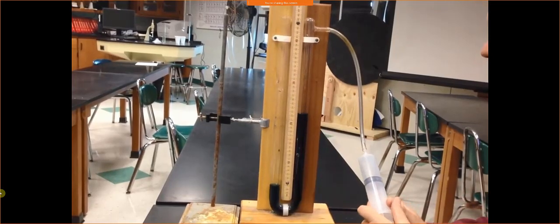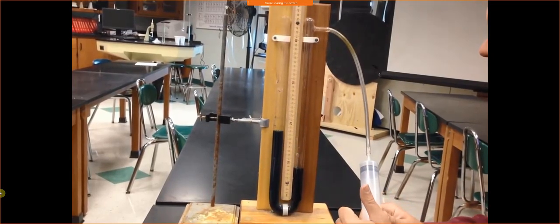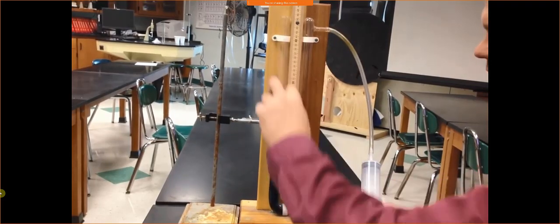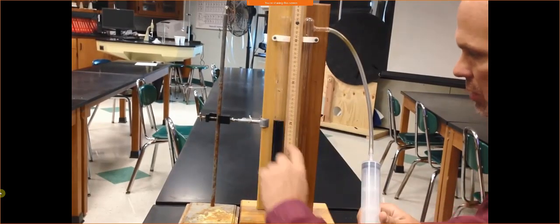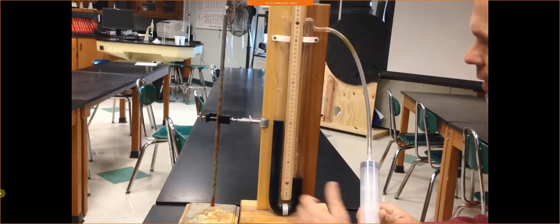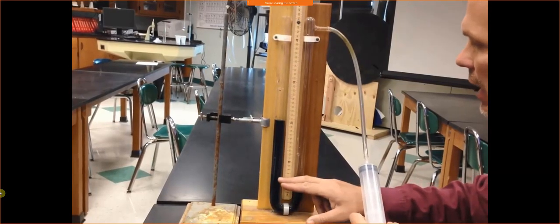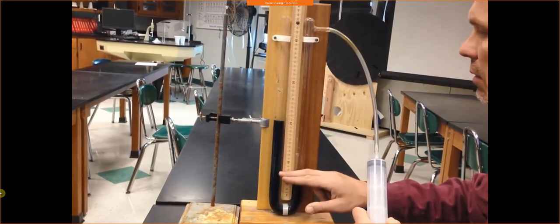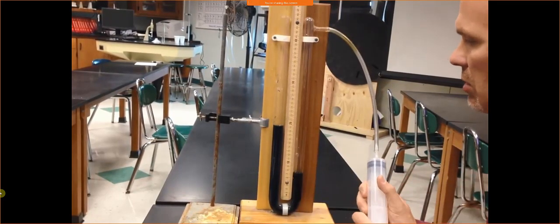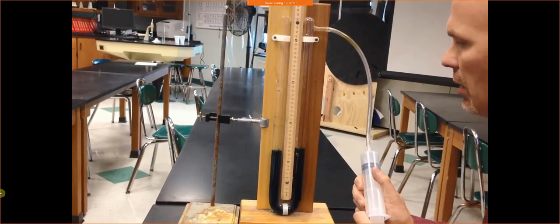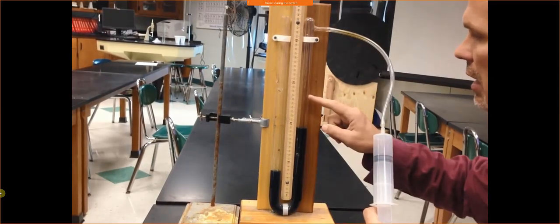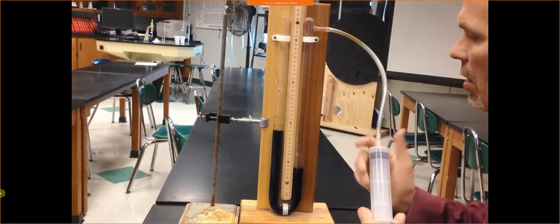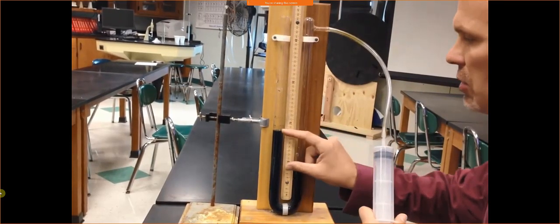When we did the other side, we increased the pressure. We said this is pushing back on the atmosphere, plus it's supporting the column. So this is equal to the pressure outside, but you have to add 190 to it in this case. So manometers are used this way. Here we're equal. Here this side is less than the atmospheric pressure pushing down by this much. And here, the gas is less than the atmospheric pressure by that much.